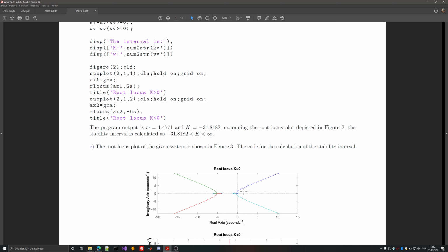And then this is leaving the left half plane. These poles are leaving the left half plane earlier than the previous version, because it does not have that much distance, and it has a more aggressive angle, so that it will more likely cross the j omega axis earlier.